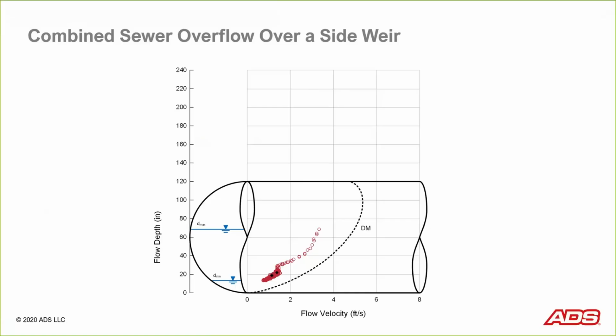Well, I've actually went back and got the design parameters on this particular monitoring location, and I drew a Manning curve using the design method. So I've taken the design slope and assumed the roughness coefficient, and I show that this data never agrees with this design curve. And that tells me that this pipe does not operate under uniform flow conditions.